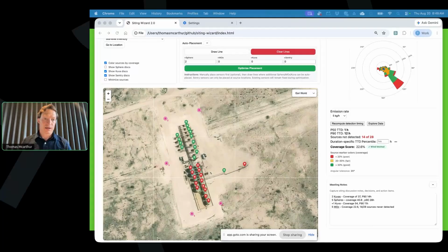So the dispersion model basically determines a distance away from each source that it can be detected if your sensor has an MDL of whatever, 0.3 ppm in this case. And because we're using hourly average weather data, we've assumed and validated that to be an accurate way of determining detection.